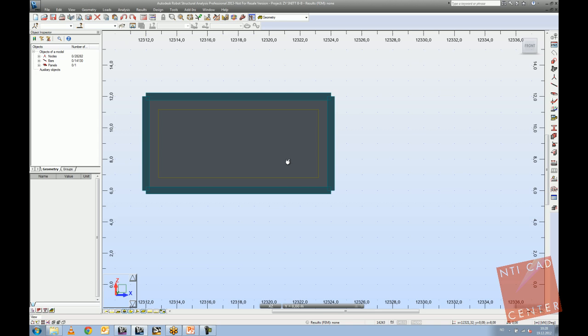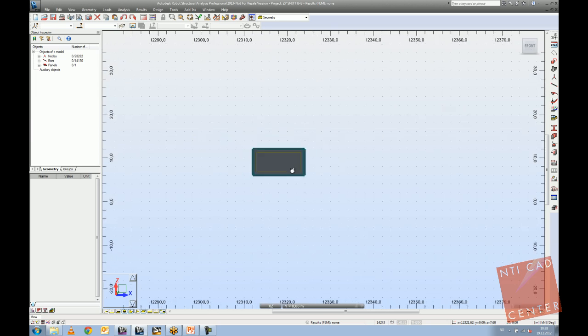So getting back to the message, again, I repeated it several times. I want to do it once more. The biggest concern that I would have when I use AutoCAD in the workflow is actually the accuracy, that AutoCAD is too accurate. So before importing any links or actual data from AutoCAD, you always need to clear it up. You need to check the nodes. You need to be sure that you don't have some inaccuracies.